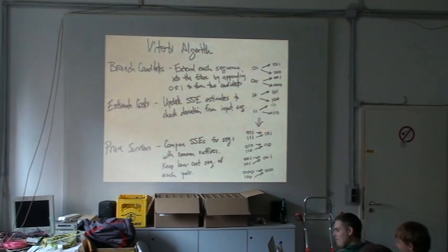Then in the third step, you're going to take all these candidates, and for candidates that have common suffixes, you're going to choose the one with the lower cost. So you're going to go back and group the candidates together in a different pattern than when you branched them. And then within each group, you're going to take the one minimum cost. And somewhere among all these survivor sequences, there's going to be one that has a global minimum cost, and the global minimum cost is your best fit symbol estimate.